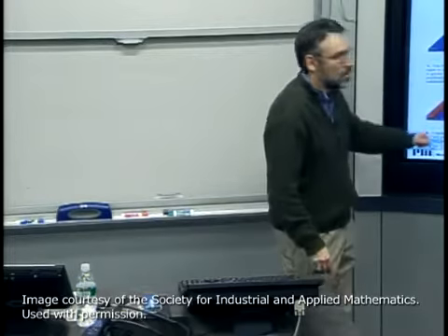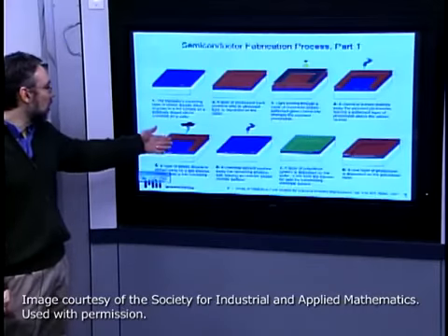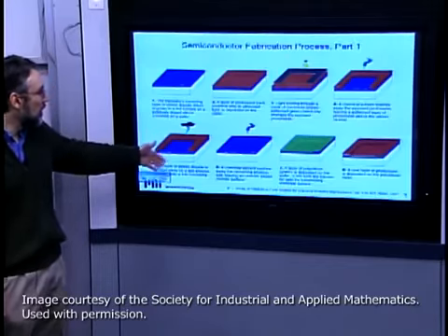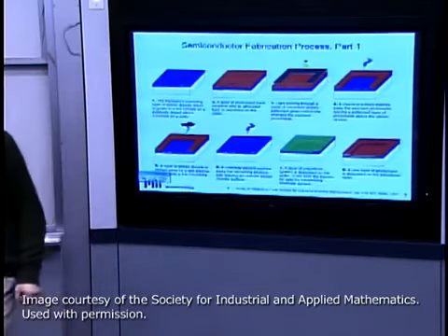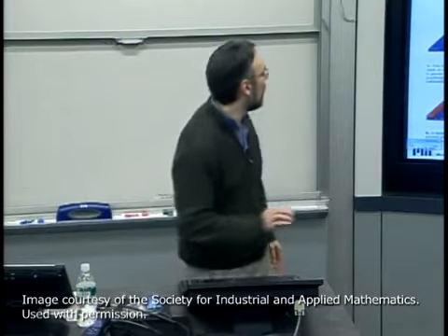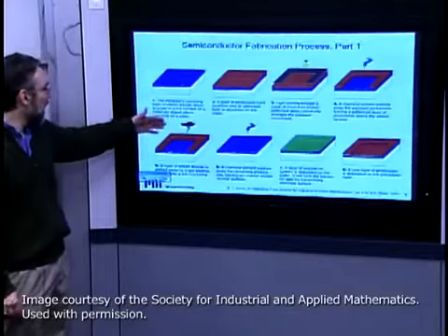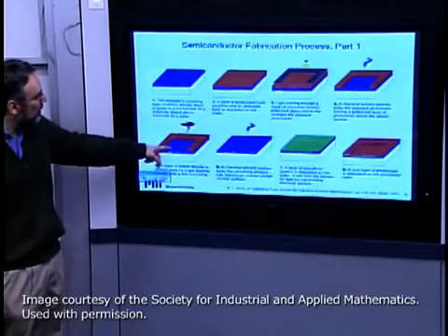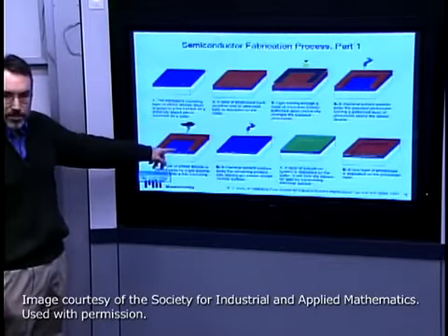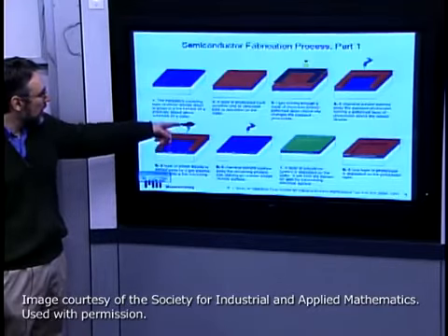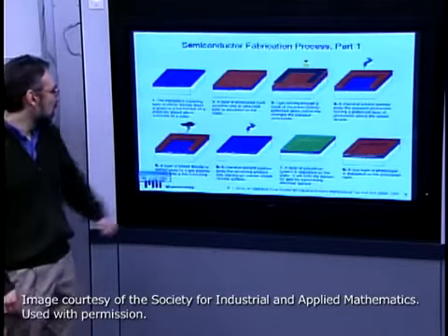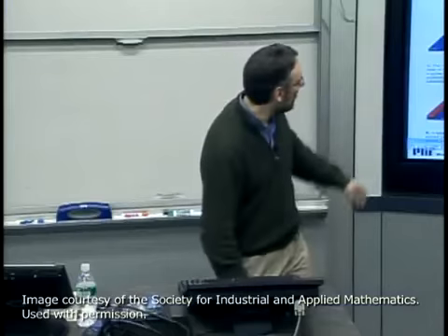Its purpose is to act as a mask to allow us to differentiate more aggressive physical transformations of the remaining wafer, and in particular in the following case, as shown here in step 5, this is saying what we want to do now is do another etch of the silicon dioxide layer, in this case using a gas plasma etch. I guess that's what the little lightning storm here is.